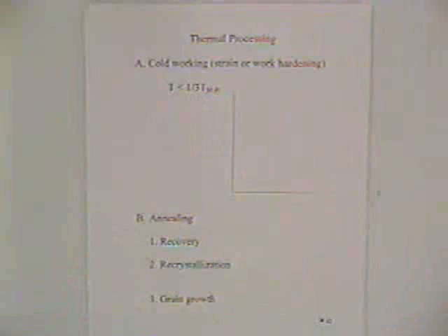And the first thing that we're going to talk a little bit about is cold working, or strain hardening. Now in the mechanics sequence you've talked about a tensile test, and we'll just touch on it here in a minute. But once you exceed the yield point and the material starts to plastically deform, and when you remove the load there's some permanent deformation, that process is called cold working if it's done at room temperature or less than about a third of the melting point, or strain hardening or work hardening.